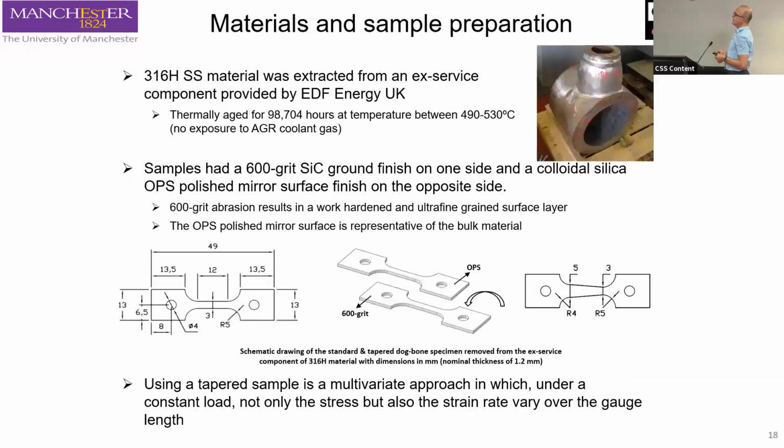So the experiments were conducted on a thermally aged material. It's a material that was extracted from an in-service component, and the component was thermally aged for almost 100,000 hours at high temperatures. And from this material, we extracted oxidation coupons, as well as samples for creep testing.